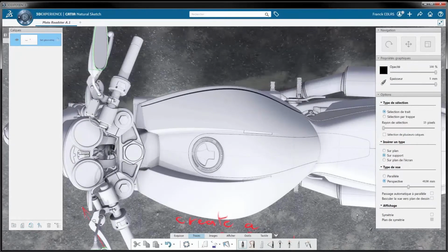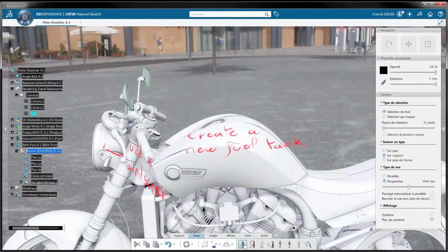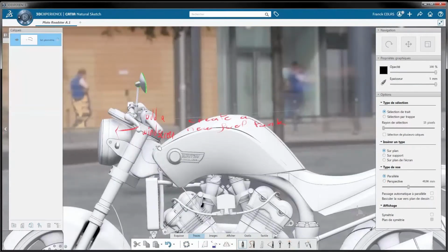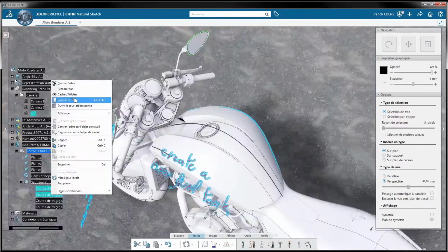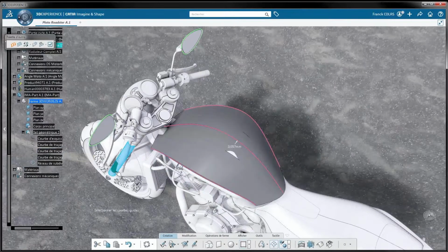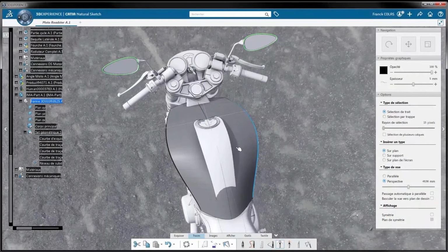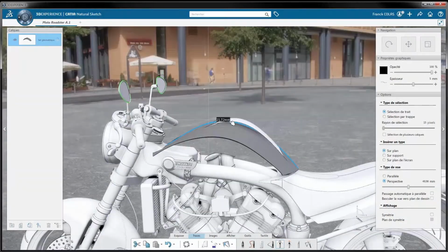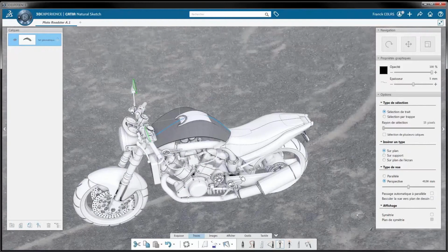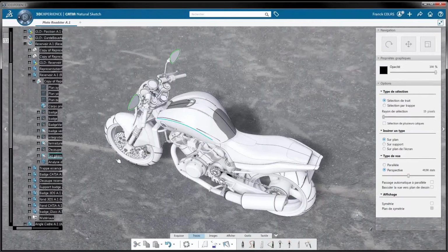And so while in the same sketching application, Natural Sketch, we can easily sketch out our shapes with vector or raster-based 2D or 3D curves. So we're drawing these new design ideas for the fuel tank. We mirrored it, and then we actually lofted a surface through there and can manipulate the actual 3D curve and watch the tank surface update.